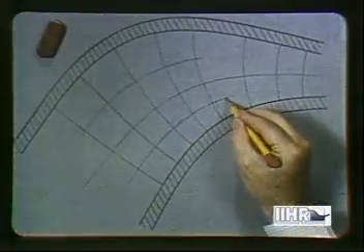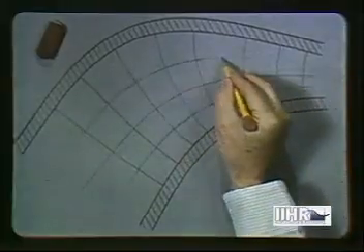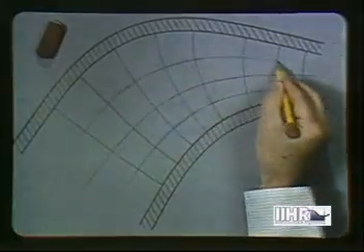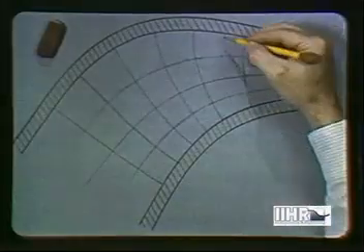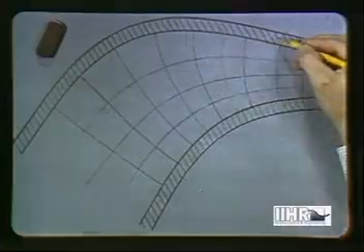Now, the important part about irrotational flow is that the flow pattern can be approximated graphically or mathematically by the construction of a network of streamlines and normal lines, which are so spaced that they divide each other locally into equal parts. As may be shown mathematically, for any shape of the solid boundaries relative to which the fluid moves, there is only one correct flow net. And after a little practice, with plentiful use of the eraser, its first approximation can be very rapidly sketched.